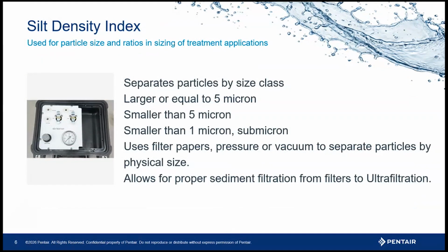Now, sometimes we run across wells or water systems that have a ton of fine particulate. And a lot of times it's wells, depending on what you hit. You may hit fine sands, you may hit clays that have a very fine sticky silt to them. And we really want to identify those situations because those need special needs. There also are some municipal markets in the United States that require special filtration needs as well, like Seattle, parts of New York, where you still have wooden water mains in use. So high levels of silt in those communities in different locations.